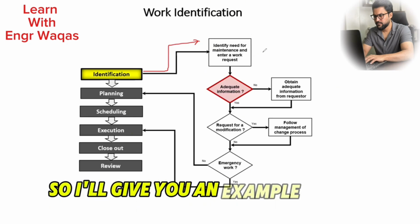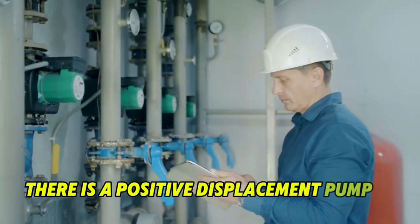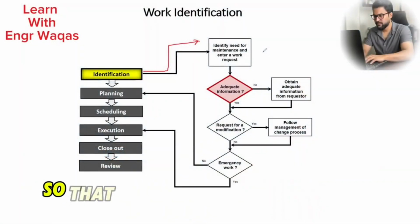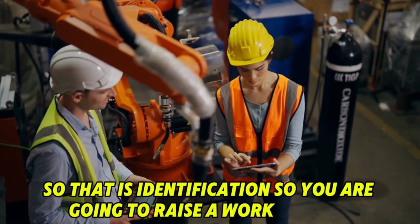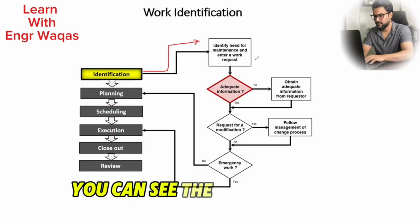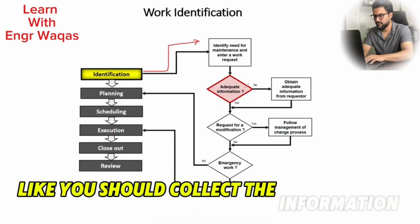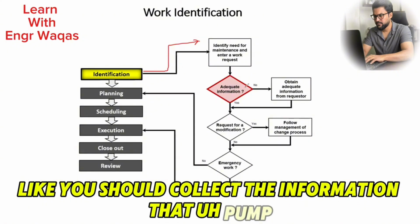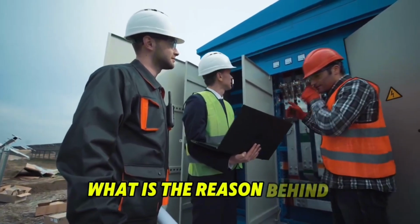So I'll give you an example. You're working on a plant, an oil and gas refinery. Let's say you identify a positive displacement pump is not working properly, so that is identification. So you are going to raise a work request. That is the first thing. Then after that, you should collect adequate information: why that pump is not working properly, what is the reason behind the malfunctioning.